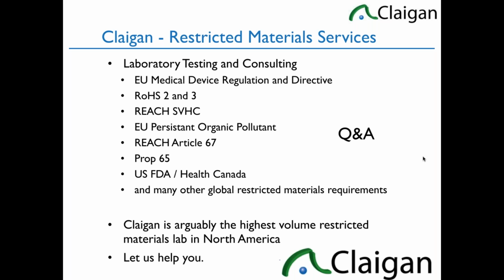What RoHS is really around is preventing exposure, not to the user, but preventing exposure to the recycling worker of 4 heavy metals and 2 brominated flame retardants. So it looks at what materials are part of the product upon recycling. So consumables that are used up, non-electrical consumables, like printer cartridge ink. Printer cartridge electronic, it's in scope. Printer cartridge ink is not in scope of RoHS. But all other components that are part of a medical device that's electronic in nature and intended to stay with the medical device for its lifetime are in scope.